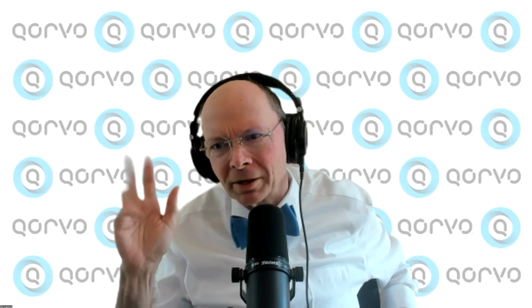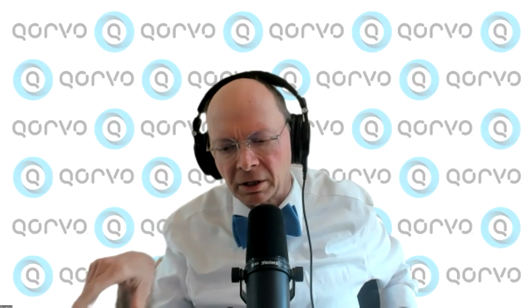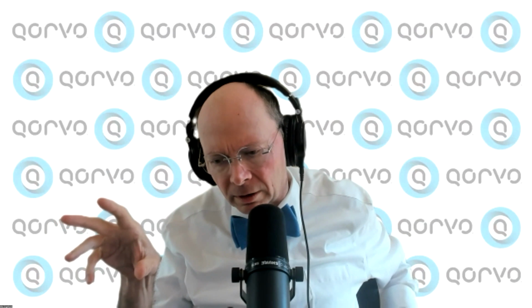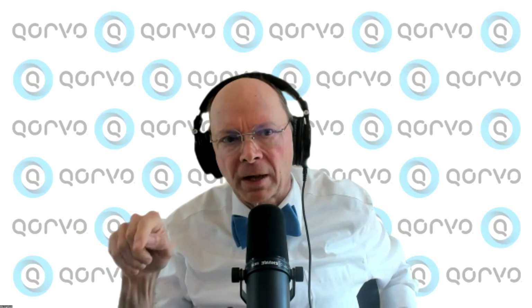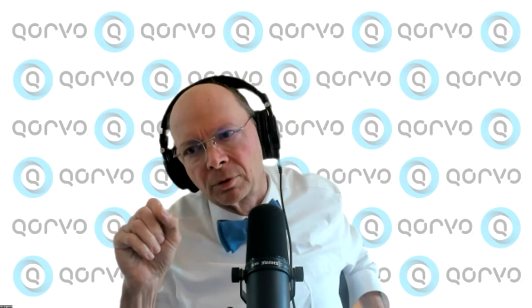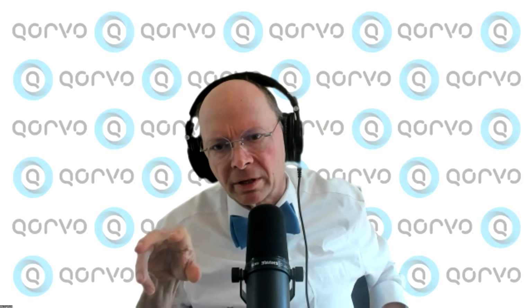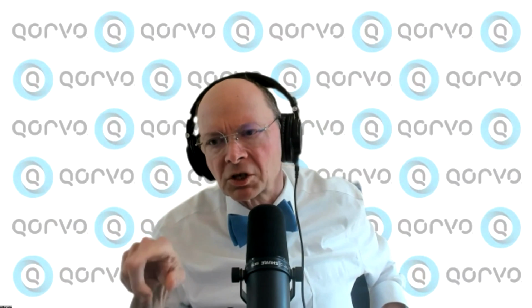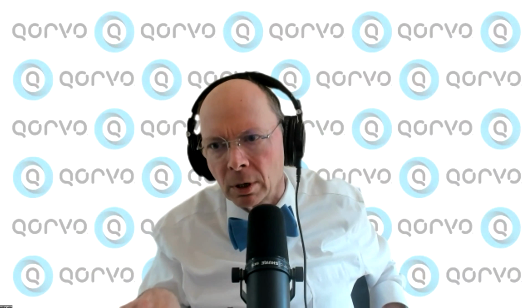So there's no way the Cloudlifter has as low noise as a properly designed circuit like the FET Head. So I used more of the FET Head design, except that the FET Head doesn't terminate the mic in the way I like. You really don't want to put the termination from plus to minus. You want to put it from minus to ground and plus to ground. That way you short out the common mode noise, because you have this dynamic mic, which is a little antenna.